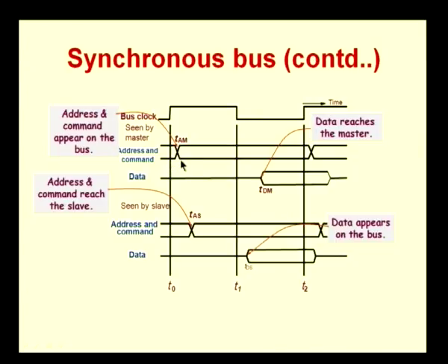Okay. This is when it will actually appear on the bus. It will appear on the bus, and it will have to be on the bus, as we said, for a little time after the data has been strobed in. You can see that this value remains on the bus until the end of the clock, and also for a little bit of time after the clock. That is what you need to remember over here. So, this is placement of the address and data, address and command.